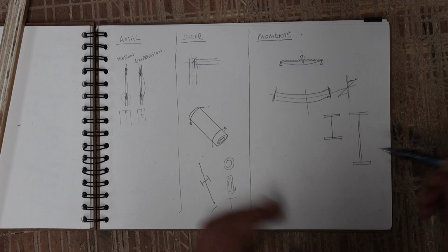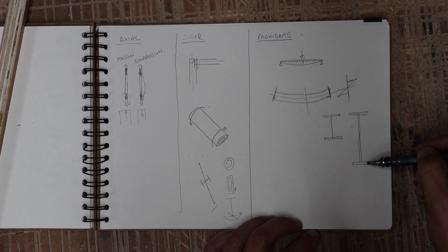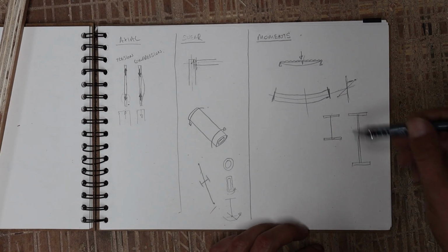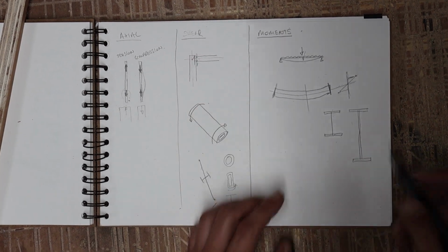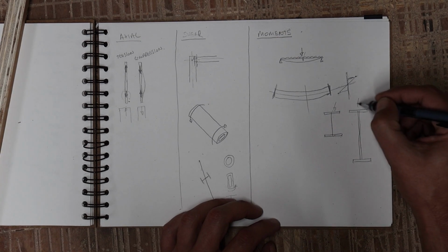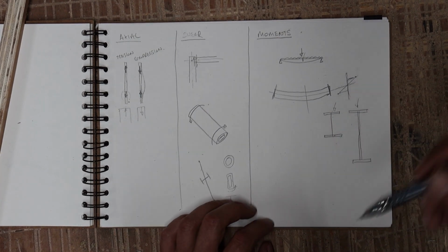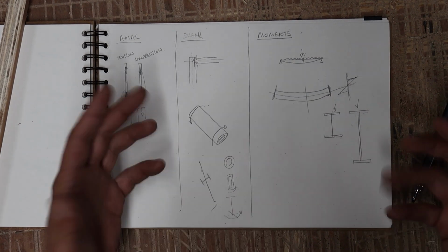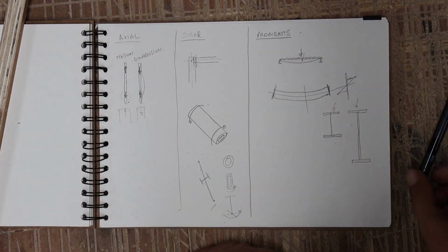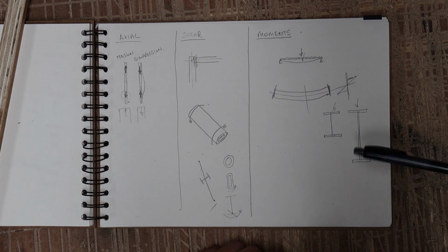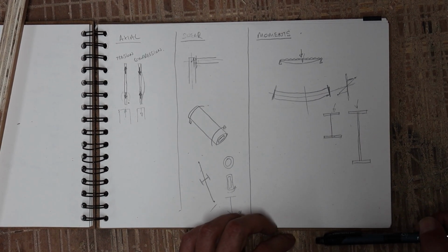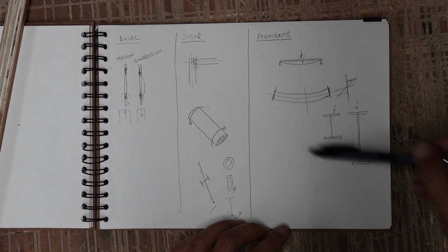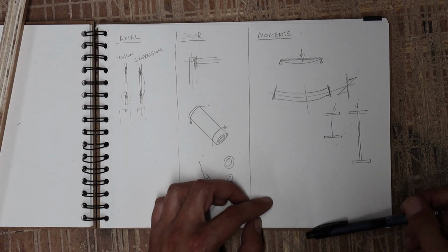I've got a book of beams. I've said this before, and there are beams that are deeper, but narrower and lighter, and they've got double the amount of strength for the amount of material in the beam. If you have two beams that weigh the same, then they're using the same amount of material, and then the strength is just a measure of how effective that beam is at supporting the force that you're putting it under. So deeper beams are much more effective, much more efficient. But people don't want big beams in their houses. They want their head heights. So we use shallower, heavier ones. That's how it works.